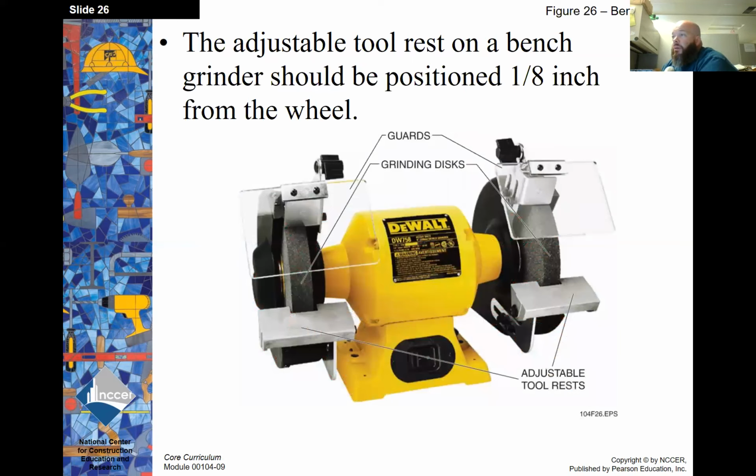A bench grinder. The adjustable tool rest on a bench grinder should be positioned 1/8 inch from the wheel.